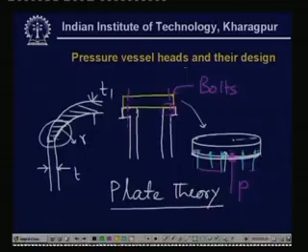So, this is to be designed according to plate theory. Now, those are again tabulated. There is various literature available on the plate theory, and normally in a design handbook you will see different kinds of figures, and depending upon the loads etc., we will have the different dimensions. The most important dimension is this thickness, which is to be selected from this theory, that is, if you look at the table, then you will be able to select that.